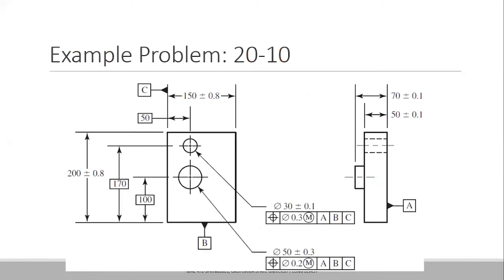As long as your faces are 50.3, the inside doesn't really matter if it's curved or not. The inside can be 49.7, 49.8, 50, but as long as the external diameter is 50.3, I am okay. And 50.3 throughout the length, not only at one section. Throughout the length, it cannot have more than 50.3 millimeters.